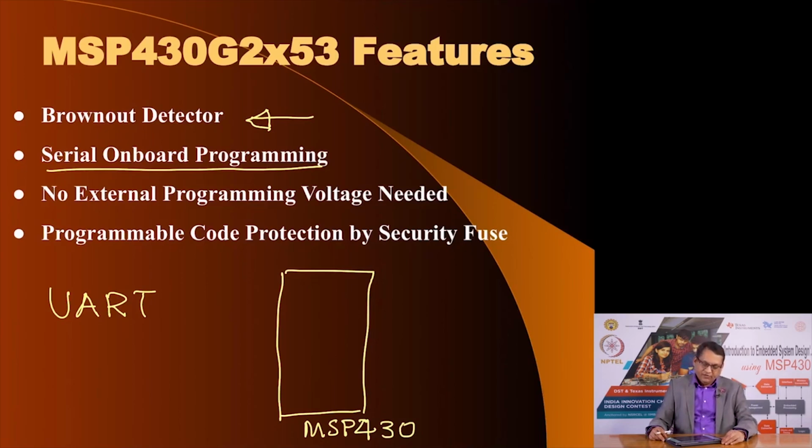setup. While programming, in many microcontrollers you require some external voltage, but in the case of MSP430 no such voltage is required, and so all you do is just connect some wires to your desktop or laptop, and you can quickly download the program.